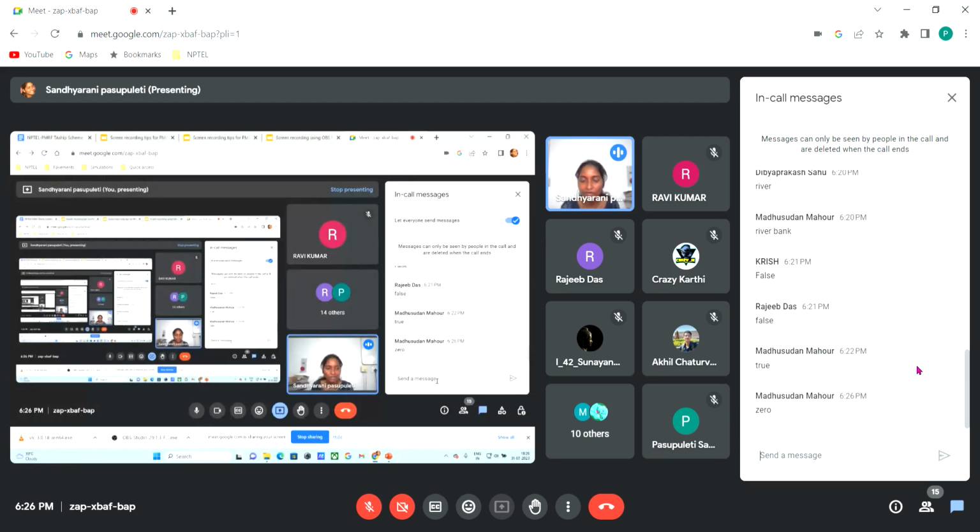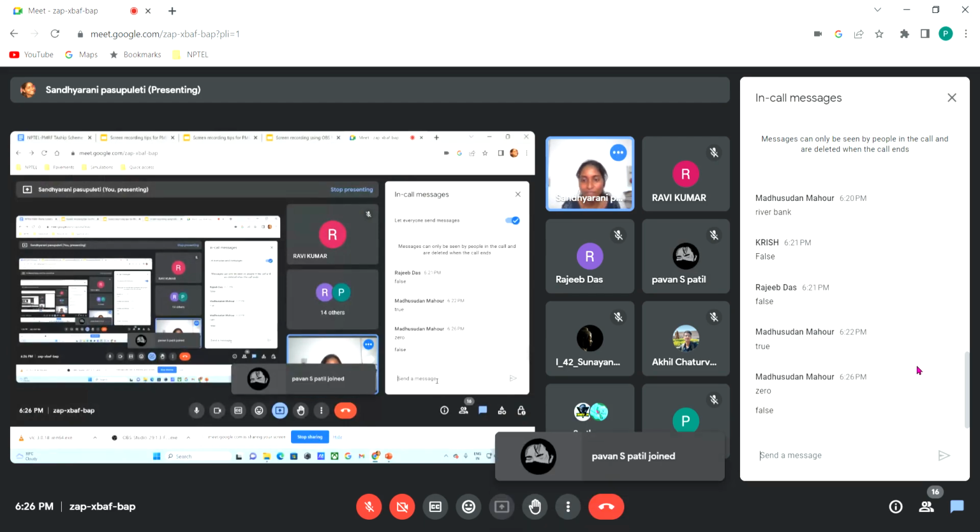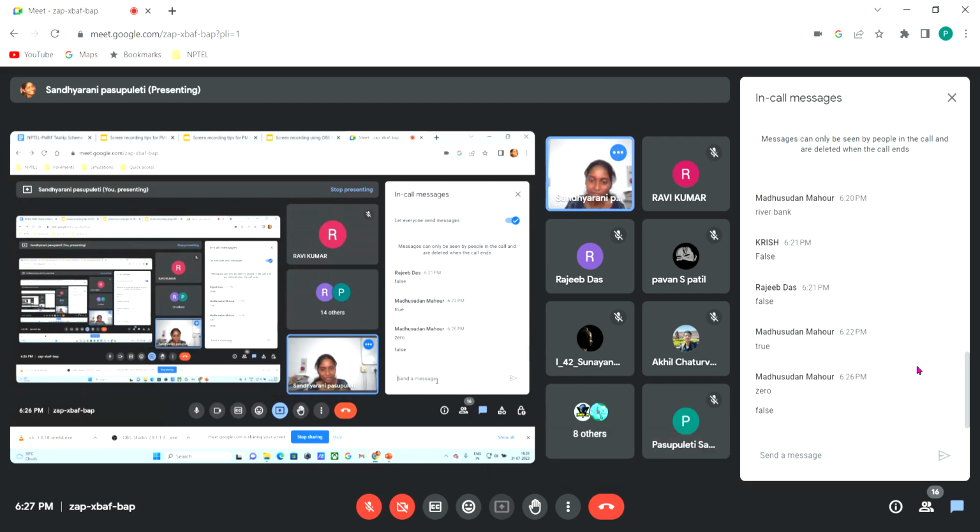At plastic limit, false. For plastic limit, you add a particular amount of water content to the soil, try to make a 3 mm thread, and roll that thread. When you are about to make a thread, you will see slight cracks on the thread. The water content at which those cracks form is what we call the plastic limit. That will depend upon the type of soil. It will not be the same for all soils. But when you consider the shear strength, it will be the same at liquid limit. That same value is nothing but zero.